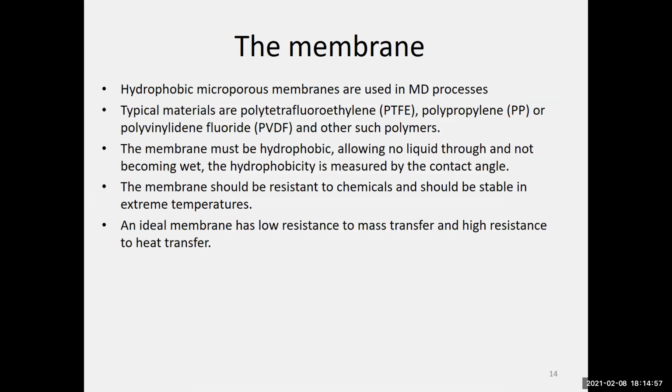Characteristics of the membranes: they are basically hydrophobic membranes. They are microporous, with very small pores that would allow the water vapor molecules to pass in. The materials that are basically used for this are polytetrafluoroethylene, PTFE. This is what we commercially refer to as Teflon. So the material of the membranes is basically Teflon.